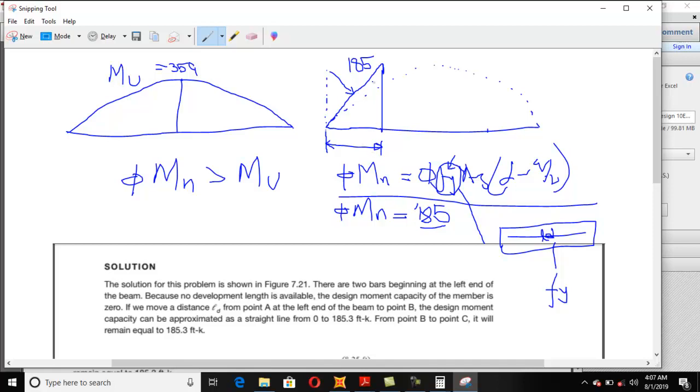And the one thing you must ensure is that at the cutoff point, the actual bending values should be less than the design capacity envelope. Okay, now after that we see that these points are below this.